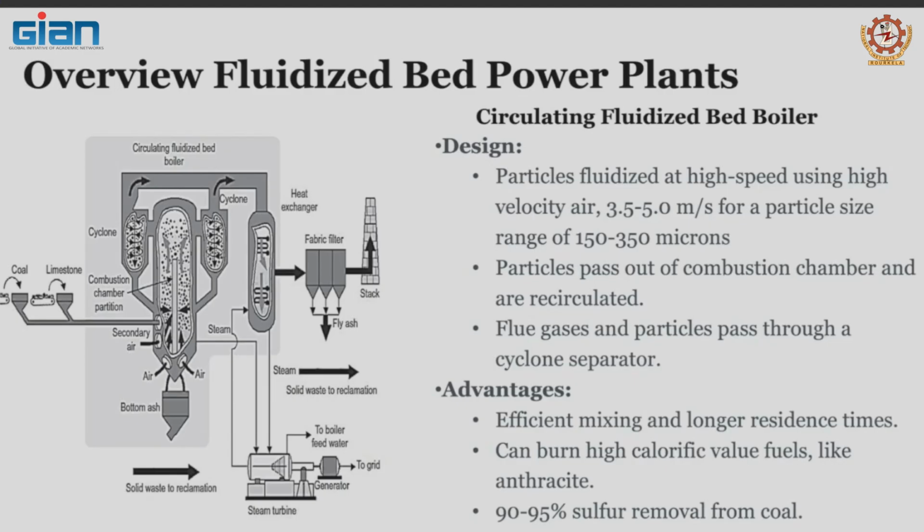pulverized boilers: in a combustion application, you need to determine, here is my fuel. In my fuel, I have this much carbon, I have this much hydrogen. These are the main combustibles. And you calculate your stoichiometric air requirement. The stoichiometric amount is a theoretical amount, so to ensure complete combustion, you add more air than the stoichiometric amount.